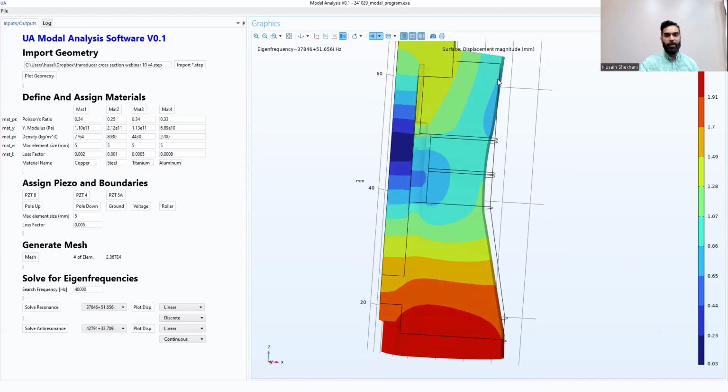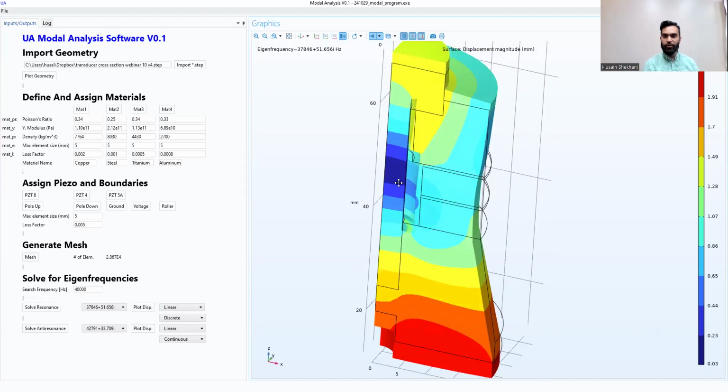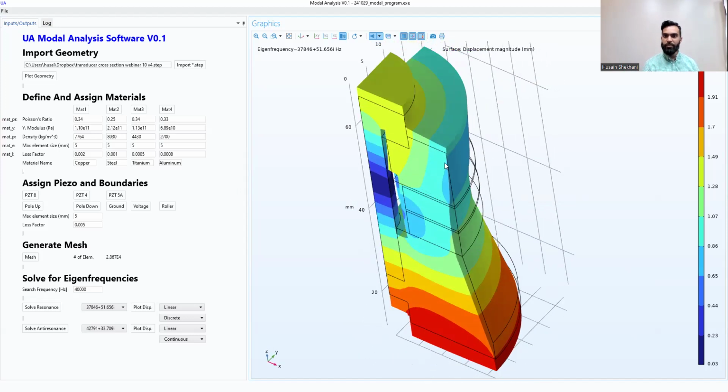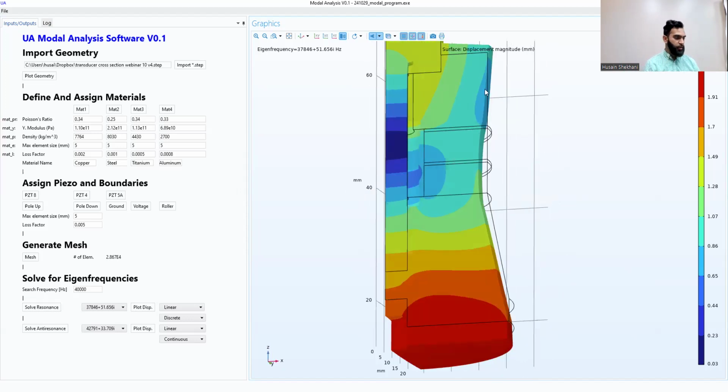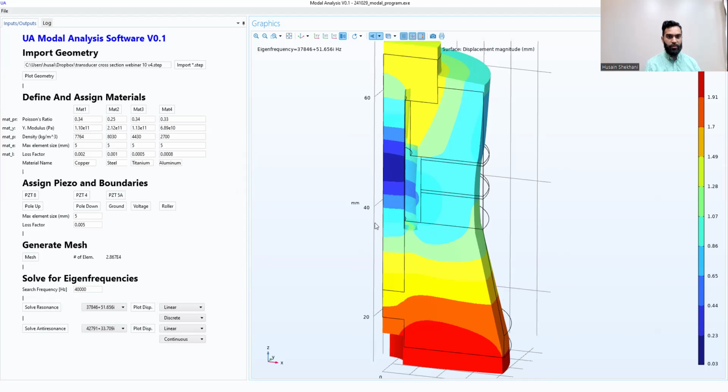It's perhaps going up and down. But yeah, that would be maybe a good spot to hold it, even on this lighter blue color. So if you machine a groove there, you were able to hold it in that position. I think you could make it work.